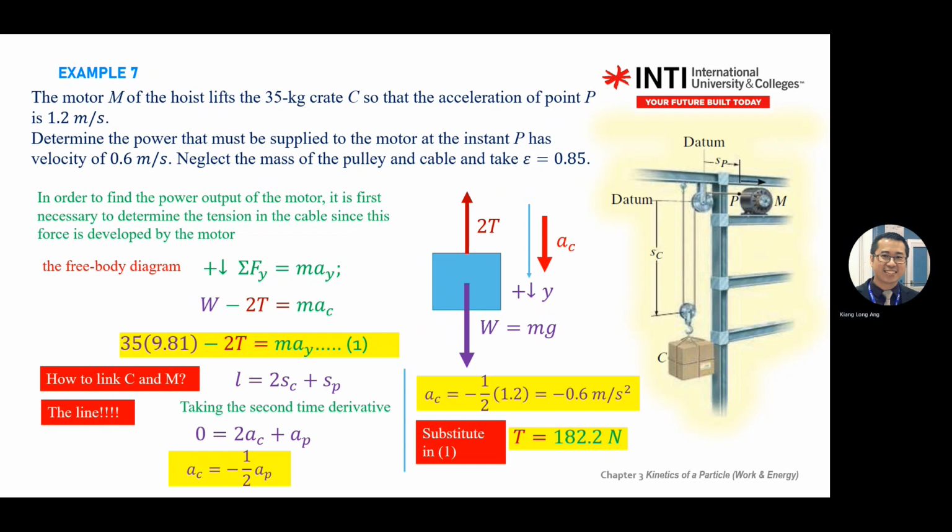What's missing? This one, you're using equilibrium of force. You need to consider acceleration, F equals ma. Here, you assume a equals 0. The previous one, you get T equals 171 because you assume a is 0. But the acceleration here is not 0. The acceleration here is getting faster and faster, so acceleration is not constant. No, velocity is not constant.